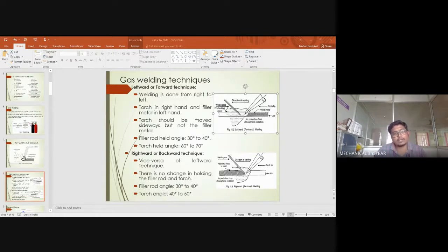Okay, but in the case of TIG welding, we will be using filler metal, whereas here the filler metal is absent. Rather than using a filler metal, here they are using a continuous metal electrode, which is also the same kind as your base metal. Next, the inert gas acts as a shielding gas, same as in TIG welding. The fused metal electrode is supplied over the surface of the workpiece, and a DC generator and AC transformer are used here in the case of MIG welding.